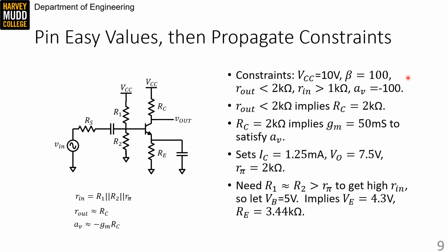Which raises a lot of questions, like could I get away with a 3.3K resistor that is lying around? And in turn, how exact does IC need to be? Which further suggests, does our gain need to be right at minus 100? These are important questions you should kick back to your client. They depend a lot on the application that you are designing this amplifier for.